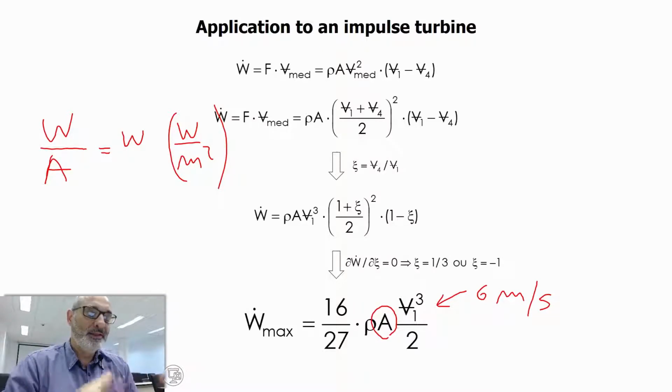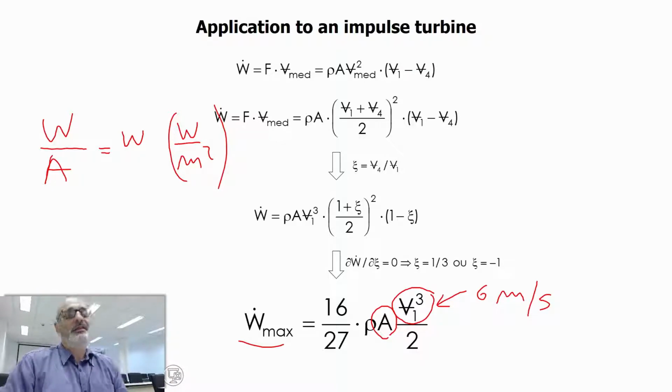And area means the number of windmills that you're going to need to generate that amount of power. So that's how you use this power. But this is a theoretical maximum. You still have to multiply by the capacity factor, because this amount is instantaneous, obviously. It would hold if you had this 24 hours a day during the whole year, but that's not a reality, that's not practical.